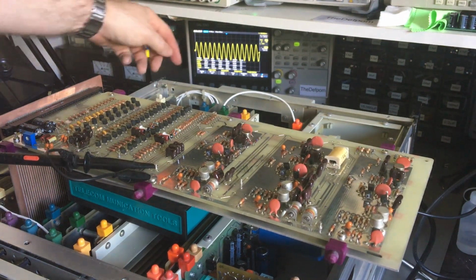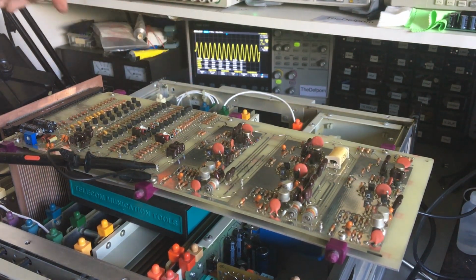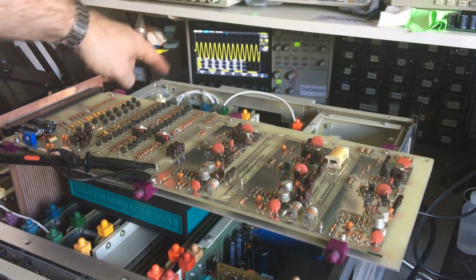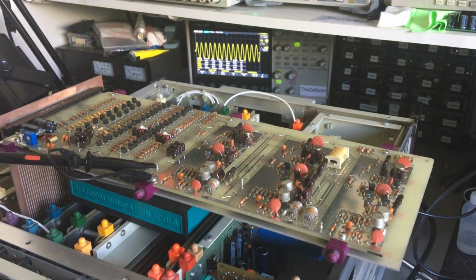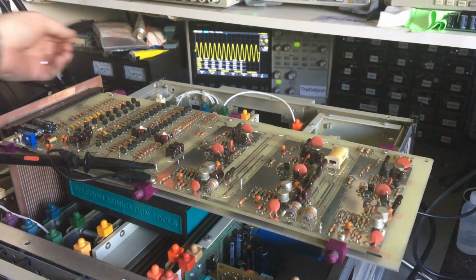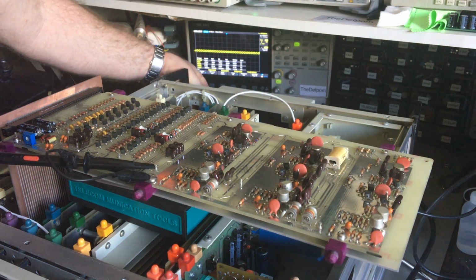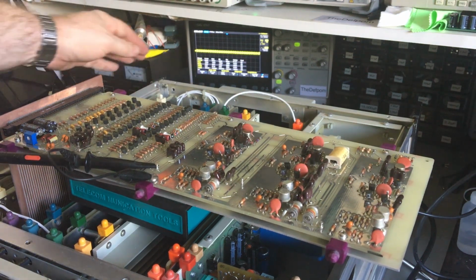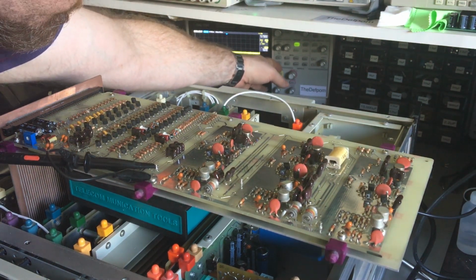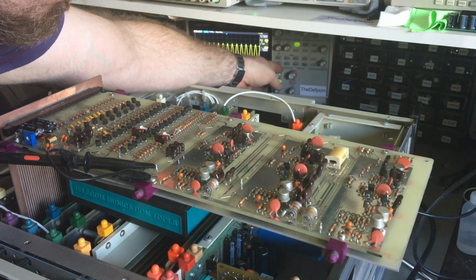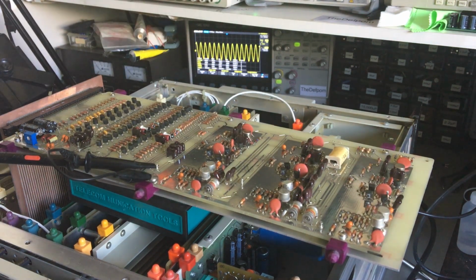Okay, so now I'm measuring the quadrature output on the back of the unit, which again is coming through this board, through the oscillator control board, out to the back, and there's a signal right there, amplified as expected, and that is measuring massive voltage. Actually, that's surprising. Hold on a second. I have my probe set on times 1 instead of times 10. Just putting this back up again. Alright, so that's 6 volts.